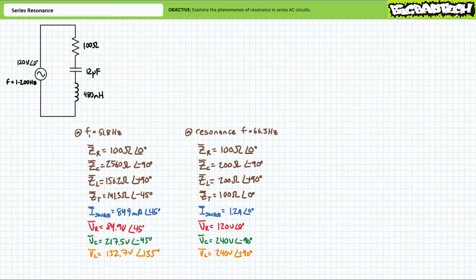As previously, take a moment to weigh the consequences of operating at the lower half-power frequency, i.e. lower than the resonant frequency. Capacitive impedance went up. Inductive impedance went down. Total impedance seems to favor a somewhat capacitive nature.